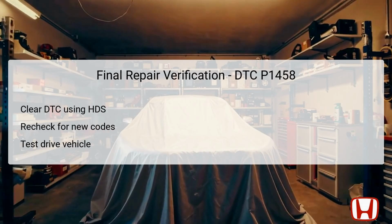After all troubleshooting steps have been completed, final repair verification is crucial. Start by clearing the DTC from the engine control module, ECM, using the Honda Diagnostic System, HDS. Once cleared, it's vital to recheck the system for any new codes or recurring problems. After ensuring no new DTCs have appeared, conduct a test drive.